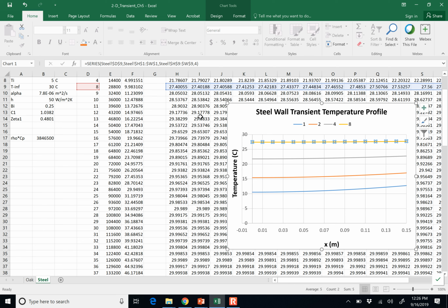Now with this graph, wouldn't we just flip it over to the other side, and that would be the full wall where you have the tiny hump in the middle? Exactly. Because of symmetry, if this were that doubly thick wall that had convection on both sides, this is just the temperature profile of half. And yep, exactly, flipping it would just show the other half.